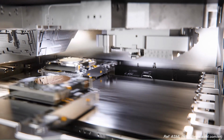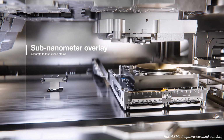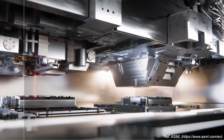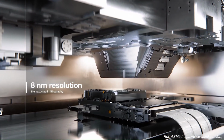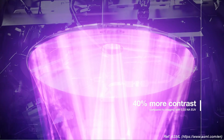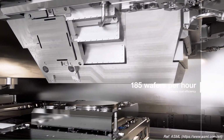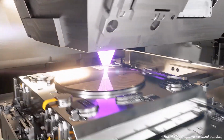Photolithography relies on advanced optics and precise motion control. It begins with anamorphic optics, which increase the numerical aperture and enable higher resolution. Faster stages ensure high productivity, with the reticle stage reaching high acceleration. This precision makes it possible to achieve sub-nanometer overlay accuracy. Finally, the exposure process projects patterns onto the wafer, building integrated circuits layer by layer.